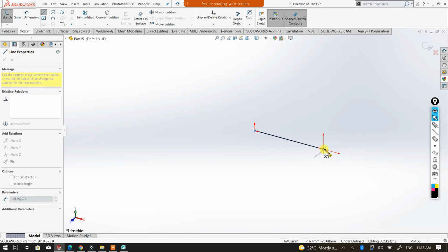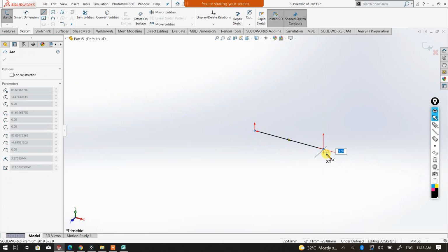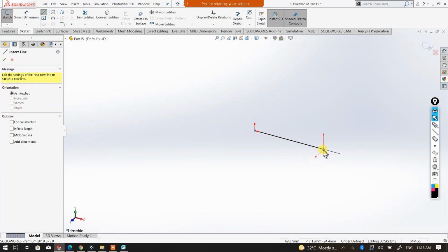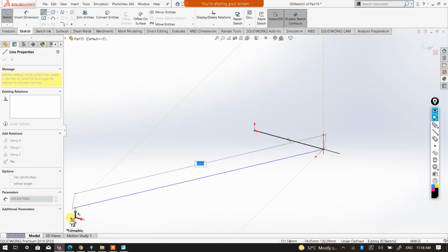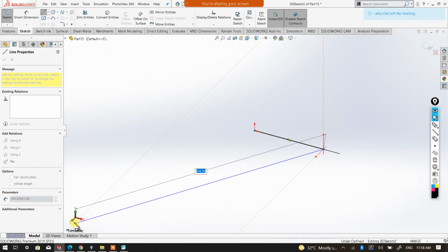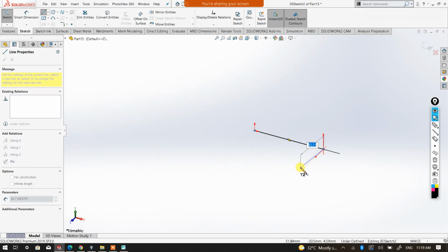And see how I'm going to change the plane. You just press the Tab button. Tab button, Tab button, see when I change with the Tab button, there you are. If you look below the pencil, the pencil icon has changed to YZ. So it means that for the time being, I am on YZ, even though if you refer to our axes, X, Y, and Z axis, you see? YZ. Now under the pencil icon it is YZ.